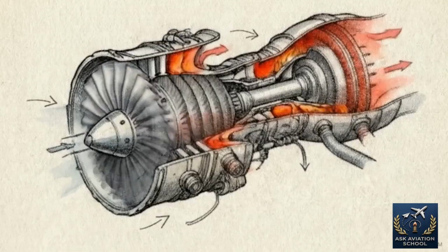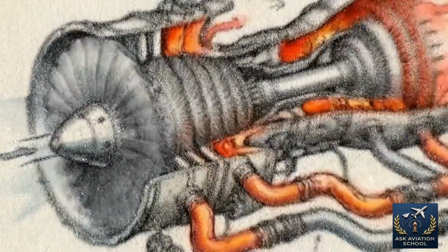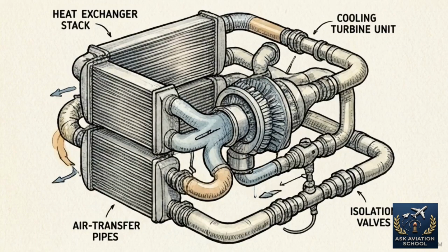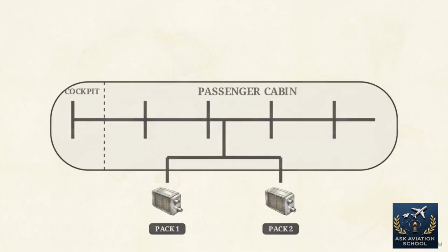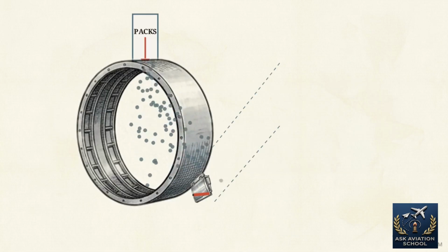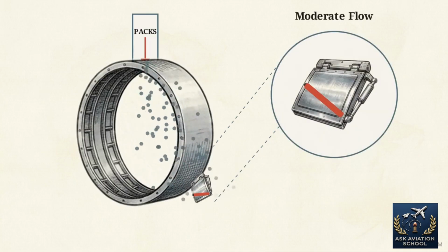Simple as that. The A320 relies on a dynamic, continuous flow of air. This airflow begins at the engines, or the APU, which extract hot, high-pressure bleed air directly from their compressor stages. That raw bleed air is sent to the air conditioning packs, where it is aggressively cooled and conditioned for human use. These two packs work together to pump a constant, unvarying mass of fresh air into the cabin and cockpit. With air constantly entering, we regulate the environment through a single exit, the outflow valve at the lower rear fuselage.